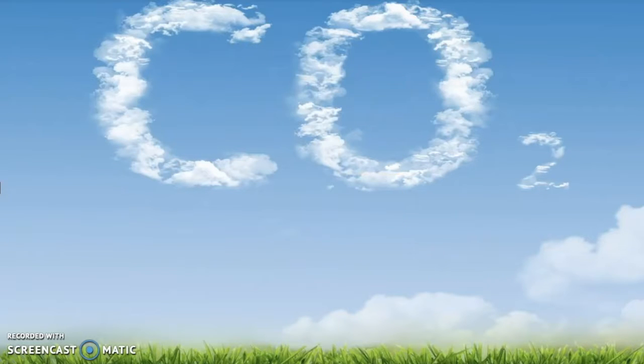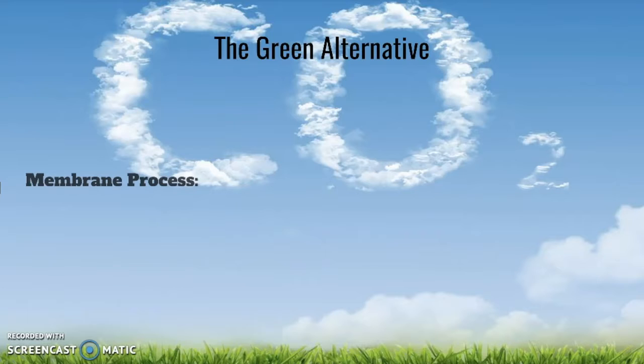Now, the only issue with this method currently is that, first of all, the amine solvents must be kept at quite low temperatures to keep them in liquid form, which first of all takes energy. And also the amines have the possibility of degrading, which leads to inefficient carbon dioxide capture. So this is where the green alternative steps in. The green alternative is known as the membrane process.